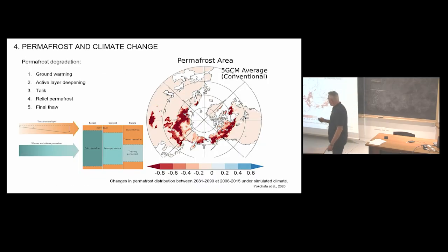Yeah, so what happens with this permafrost degradation? First, we warm the ground. Then we increase the active layer thickness. And this is all the catastrophic geomorphological manifestation that we see, because we arrive in the ice-rich zone that I presented yesterday, the transient layer, intermediate layer, it's full of ice, but it's not for a big thickness. So you have a super strong reaction, but it will not last forever. Once you're done with this ice-rich layer, all the processes will start to relax a little bit.